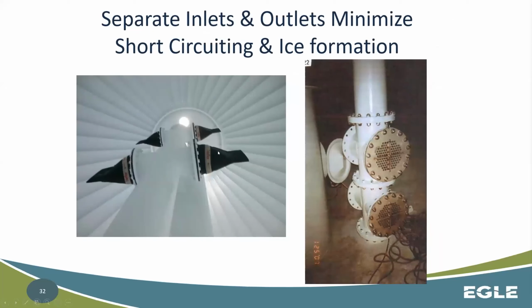This picture on the left here is what we call a duckbill valve, I should say. Basically, water's coming up and out these ports. It's going to be just a rubberized mechanism here. So with a little bit of pressure coming up, those will actually open up and basically diffuse that water out into the elevated storage tank. Okay. And then on the right here, that's that lower point. So that outlet is going here. Okay. So water's coming up, spraying into the tank, hopefully mixing around and then flowing to the bottom and getting that circulation going.